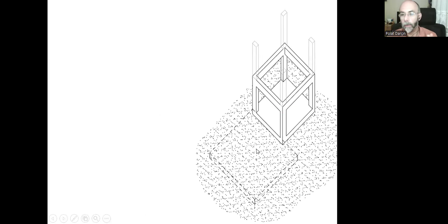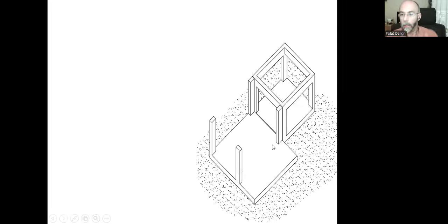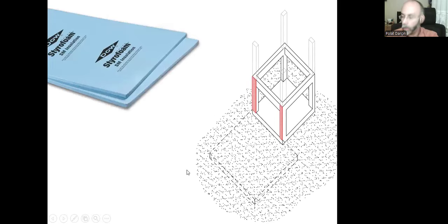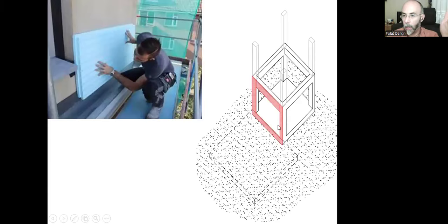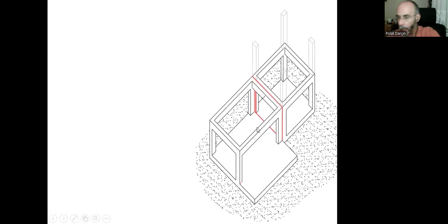During the construction, first we construct this part of the structure, that building, and we complete the construction. And in order to create the neighbor building next to it, we can use these XPS boards. You remember them from our last course. We can cover the reinforced concrete surfaces with these boards and create new molds and cast the new columns and new beams, and those will stay put.